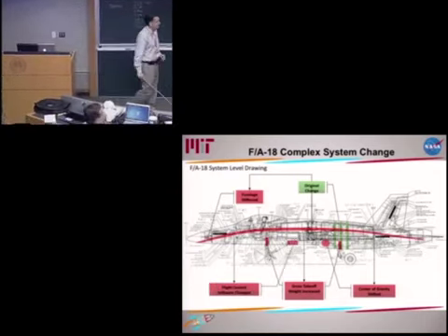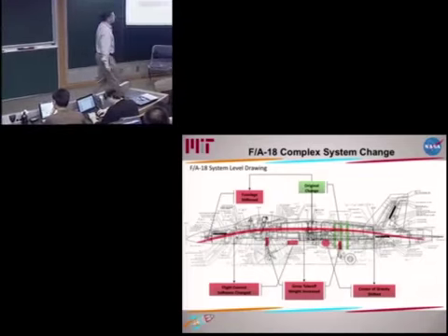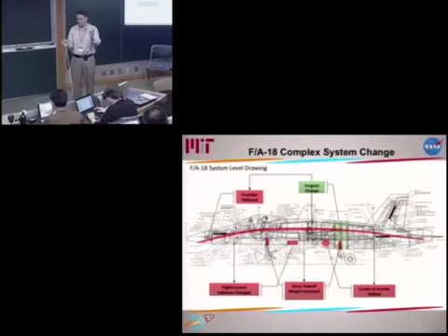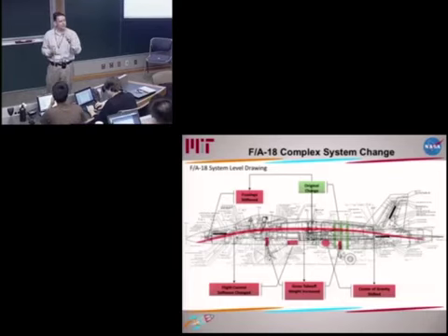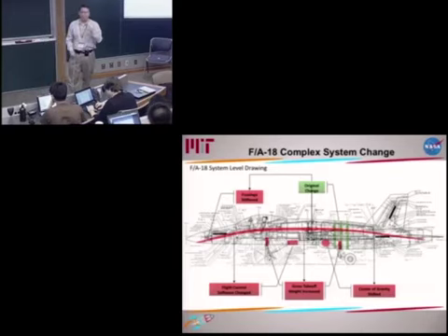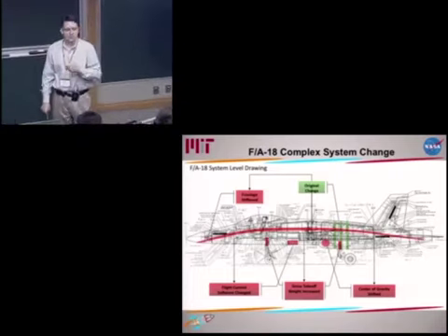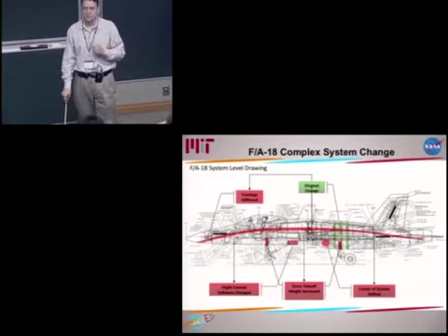So the problem now is that we have flight control software, but we've changed the properties of the structure, and the notch filters in the software are now misaligned with what they were. So we had to retune the notch filters in the flight controller. It's flight critical software, so it's like opening the box and the warranty is void. Even if you just change a few lines of code or a few parameters, you now have to retest and recertify the flight control software because you don't know what unintended consequences the change could have on other systems.